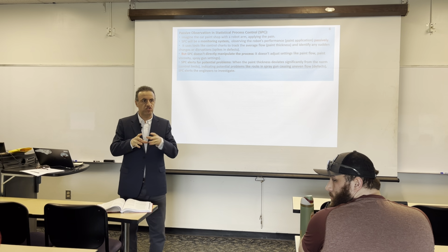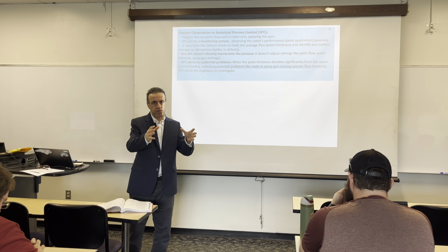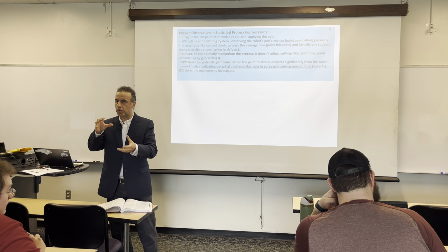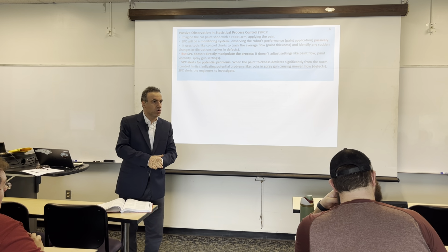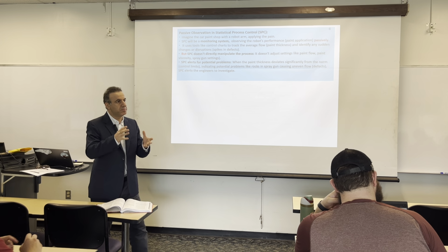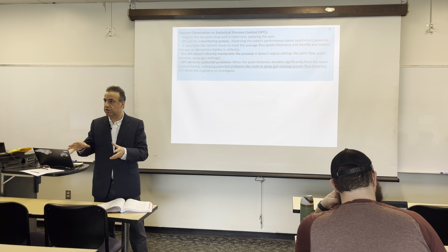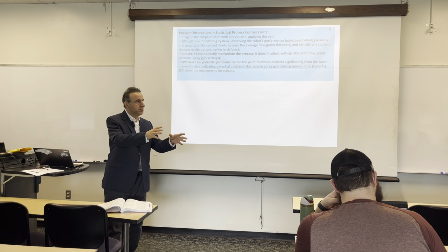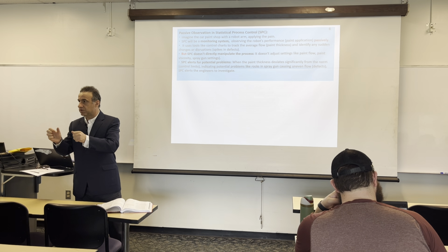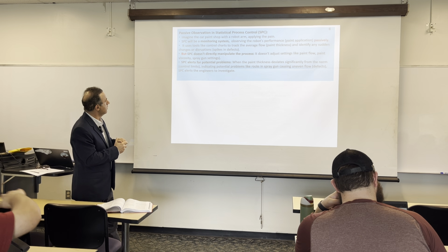So you are not changing the process. You look at the process, you collect the information, and you want to see whether your process is in control or out of control. Okay? So you're not purposely changing any factor, any parameters. You're just looking at that information, data, and then analyzing it. Okay? So this is statistical process control.